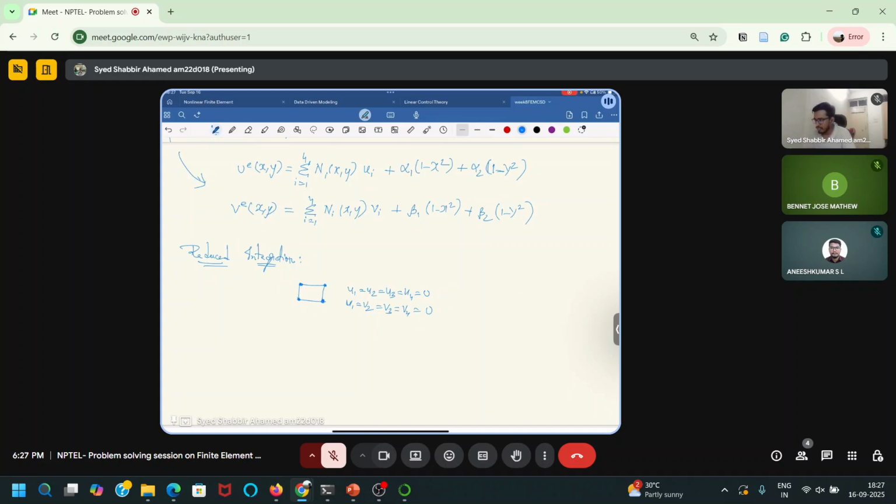So when this translates to finite element, using this four noded element, you get the elementary stiffness matrix, and the elementary force matrix. Let's say this is the elementary stiffness matrix, and these are the elementary deformations, U1, U2, U3, U4, V1, V2, V3, V4, and this is FE, the nodal forces.